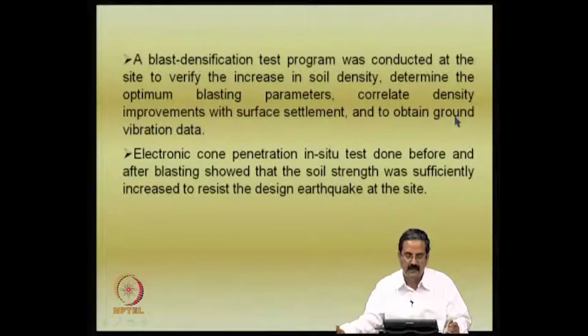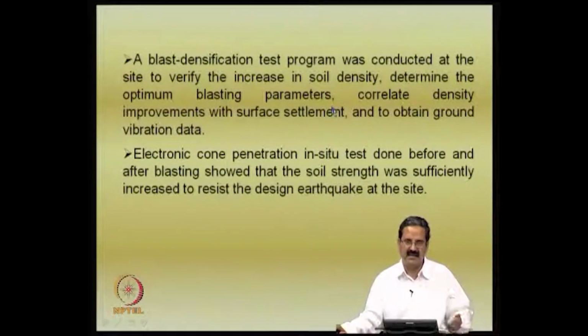So, one should measure the ground vibrations, at the surface, with depth, and in the lateral extent, and also correlate them with the surface settlements, density improvements and blasting parameters, which are nothing but the charge and the spacing and so on.